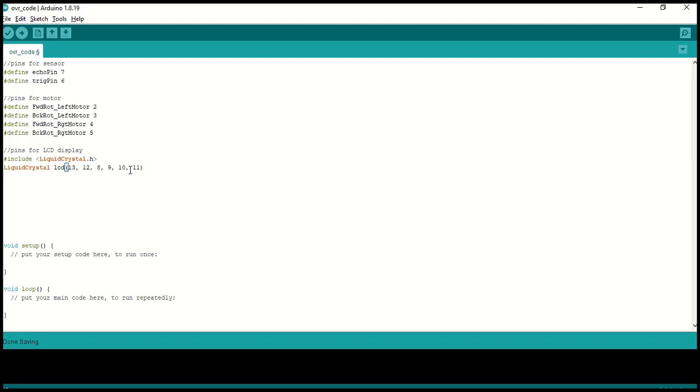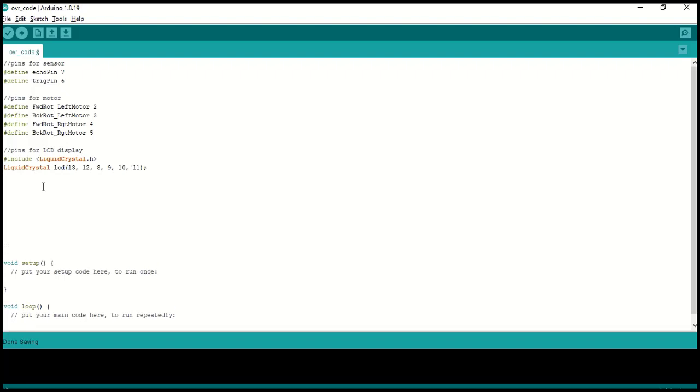Let's end this line and add a few variables so that I can store the data. First the duration, which is used for the sensor, and next is distance, again for the sensor to calculate the distance. That should be in a decimal form because that's a high value. So let me place that as a long duration, semicolon, then integer distance. That's all for the variable side.